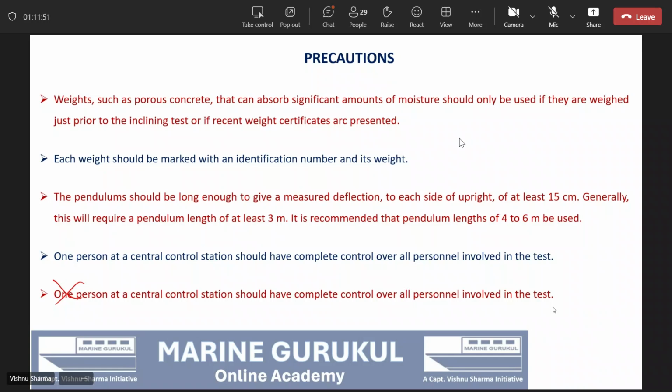When the ship has inclined and the pendulum has gone to its position, that is where you bring a bath from underneath to stabilize it, right? Yes, sir, correct. You will not have the bob dipped in the liquid when upright and then incline, because if you incline like this, the liquid will also resist the movement of the pendulum, no? So that is correct, sir.